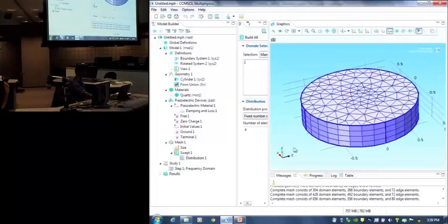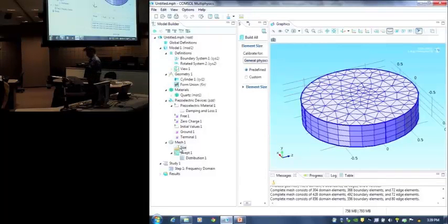You have to be very careful that the element size in plane, that is in the XZ plane, should be good enough to resolve the shear waves that will occur in this. If it's not good enough, that means you'll have to go and change the element size here and make it smaller. So for 3 dimensions, we recommend that you have at least 5 elements per wavelength. So accordingly, depending on which wavelength you're interested in, you have to modify the mesh size. In this case, it turns out this is good enough for the shear mode that we're interested in.